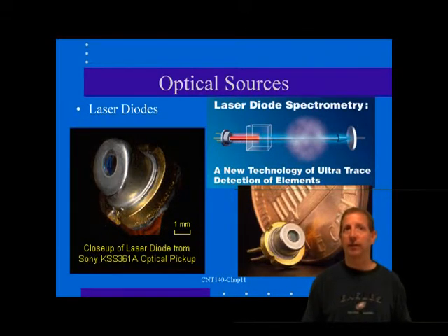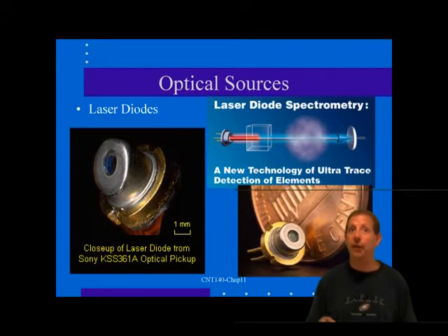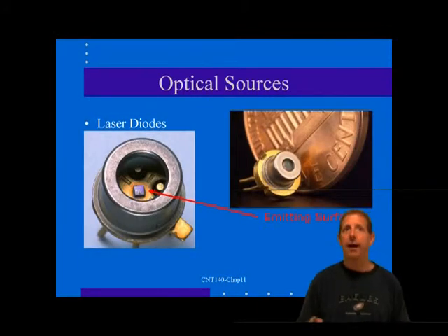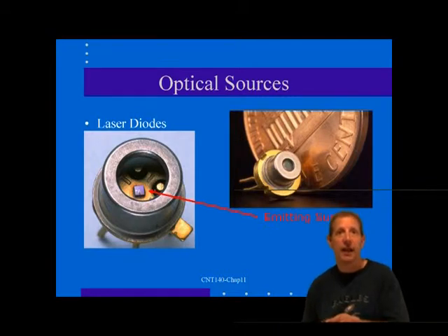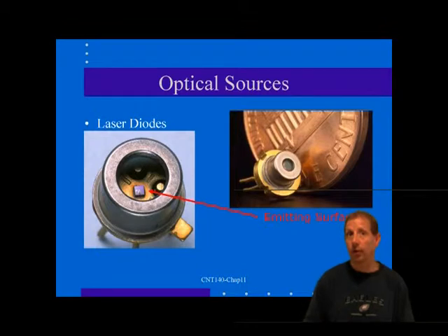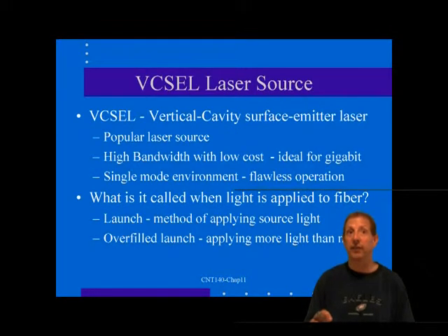Nothing to be worried about unless you launch with a laser source. Now remember that a laser is an extremely narrow beam of coherent light, on the order of 1 um for most VCSELs, that is launched precisely down the center axis of the fiber core. This means that any minor defect may deflect a substantial amount of the available light energy, causing an excessive amount of attenuation. This may in turn cause a link failure in the system.